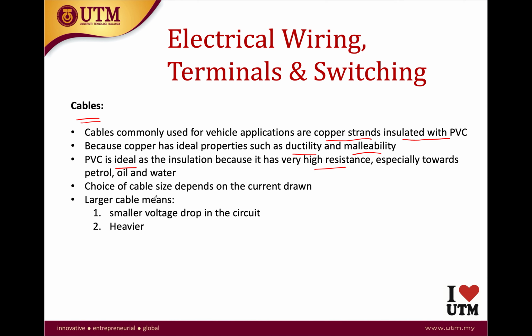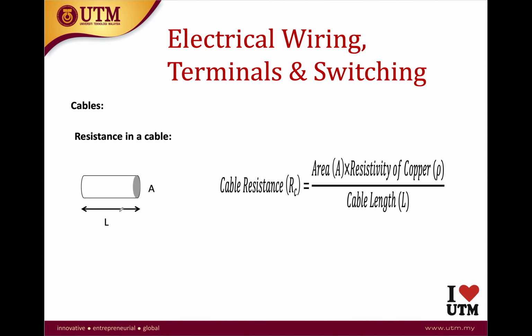The choice of cable size depends on the current that is to be drawn from the system. A larger cable means a smaller voltage drop and lesser resistance, but it will be heavier because of the weight of the larger cable. To determine the size of the cable, we need to know the cable length, the resistivity of copper, and the cable resistance, and from there we find the area.